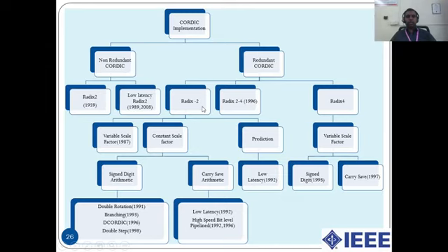Radix 2 architectures are once again classified as variable scale factors, constant scale factors, and those based on prediction algorithms. Variable scale factors were proposed in 1987, whereas constant scale factors still see improvements to date. Constant scale factors are once again represented based upon sign digit arithmetic and carry save arithmetic, which have different levels of latencies and concentrate on high speed and bit level pipeline structures.